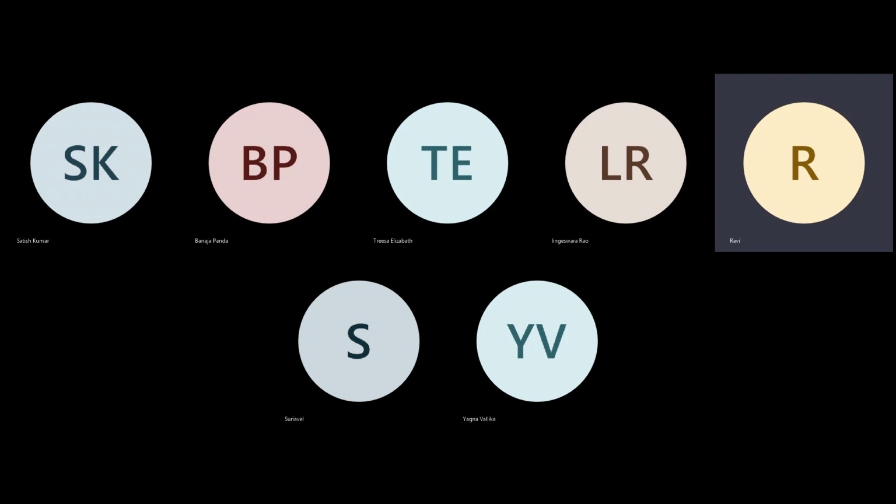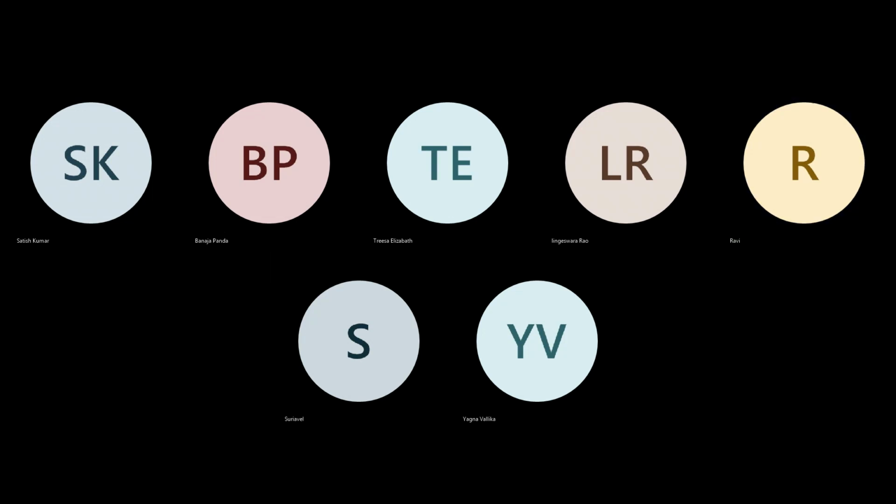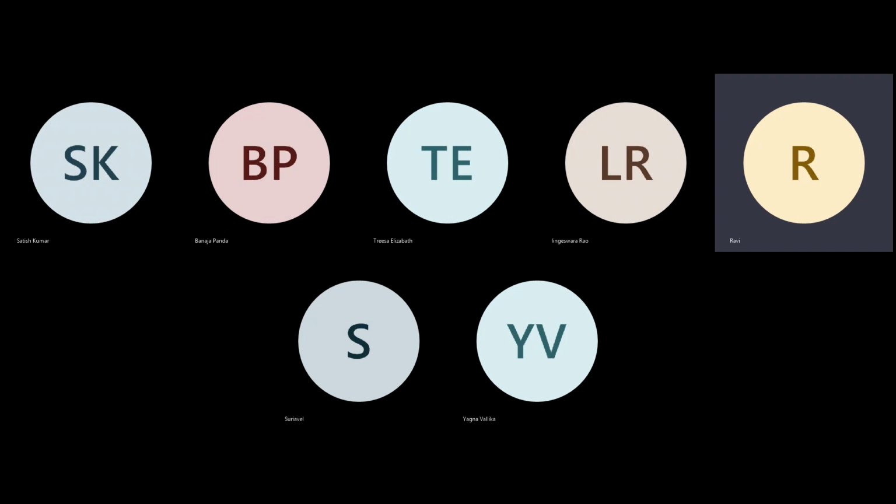Macro width. If you are actually looking at height, then see which way your cells are facing. Cells are facing bottom, or cells are facing on the right side or left side. Okay, sideways or bottom and top. Then it becomes like, okay, you have placed memories vertically over there. That longest pin has to travel the length of the macro. Too long. Let's say length of the macro is 200. Then the 200 itself is a long distance for you, right? So that's the maximum.